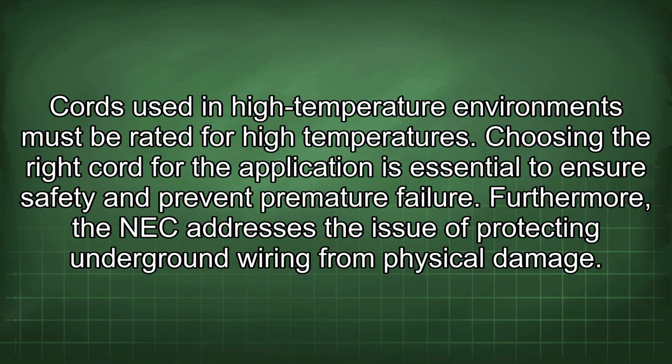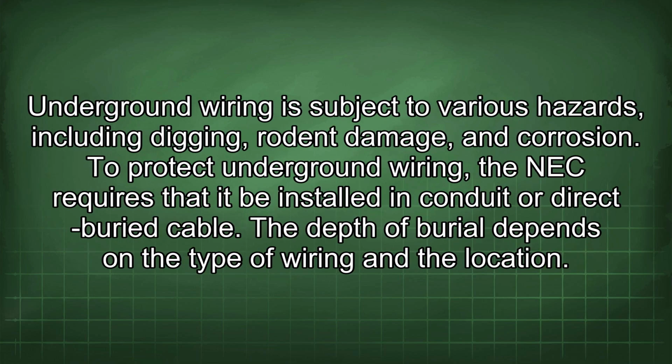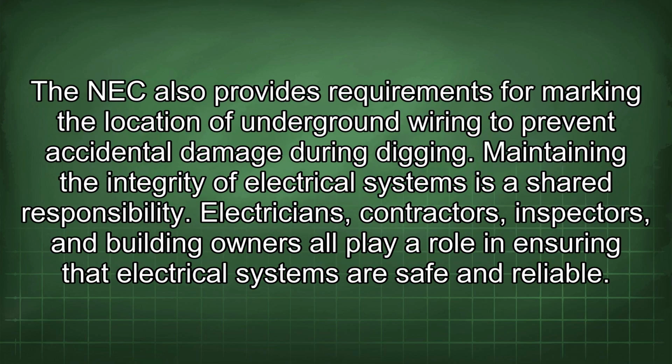Furthermore, the NEC addresses the issue of protecting underground wiring from physical damage. Underground wiring is subject to various hazards, including digging, rodent damage, and corrosion. To protect underground wiring, the NEC requires that it be installed in conduit or direct buried cable. The depth of burial depends on the type of wiring and the location. The NEC also provides requirements for marking the location of underground wiring to prevent accidental damage during digging.